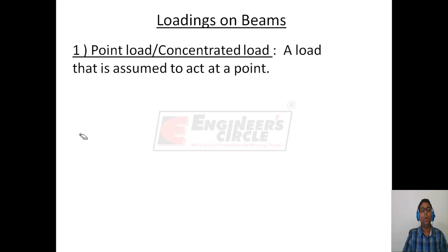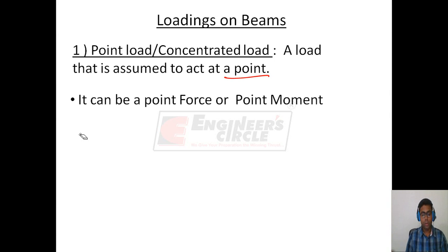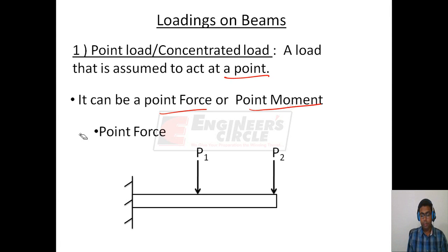Now we have seen that loadings on the beam are either the transverse load or a direct moment M. These loads can be applied either as a point load or as a distributed load. A point load, also called a concentrated load, is the load that is assumed to act at a point. It can be a point force or a point moment. For example, P1 and P2 are point forces because they are acting at points on the beam.